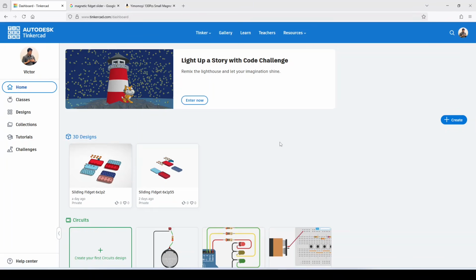You might think, well, that's only 0.35 millimeters of a difference. So what's the big deal? But if you want a friction fit, that is, you want to fit the parts without using glue at all, you will want to be that precise. And nowadays, a lot of the 3D printers actually allow you to print things that precise. And 0.35 millimeters is actually a really big gap that won't let you do the friction fit. So that's why you will want to measure them.